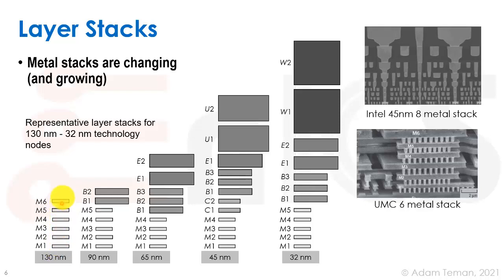They were aluminum, they had the same spacing and width, minimum spacing, minimum width, the same vias that actually connected between them. The only difference maybe was the contact layer. They were really just one single type of metal. But as we got more layers, we understood that we need to actually deliver power really efficiently and robustly to the whole design.